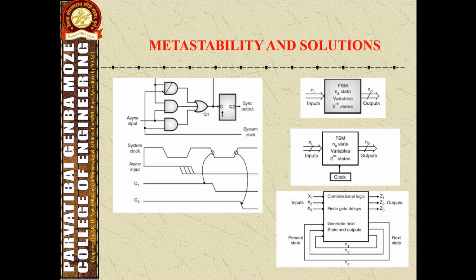So what is the sequential current state register? In this, a register set of n-bit flip-flops is used, clocked by a clock signal to hold the state vector of the FSM. For a state vector of n bits, 2 to the power n possible binary patterns are used for state encoding.